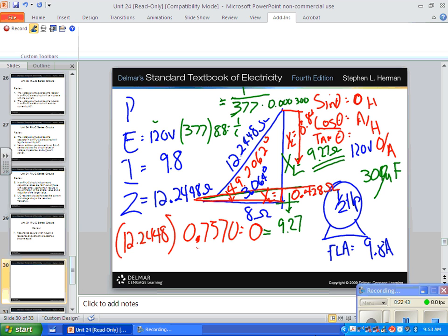Okay, what's the power factor of that? Very nearly 100%. So let's say cosine, second function answer, what's the cosine of 3 degrees? 0.998. It's 99.8% efficient. This motor just went up from being about, what's the cosine of 49 degrees? Somebody look that up. Cosine of 49 is 0.656. We took a motor that was taking in power.